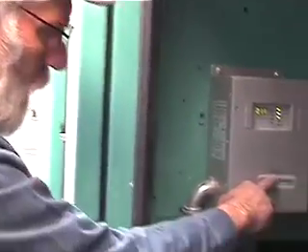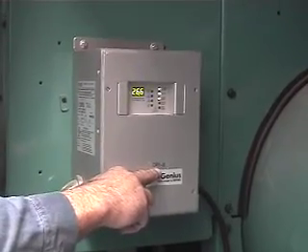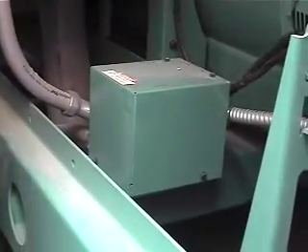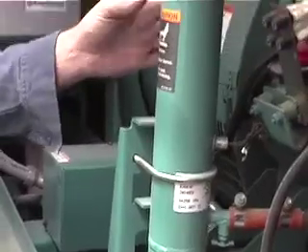Now, something I'm going to ask Randy to do here. Oh, he's already got it marked right here. OP1-8. That's going to be where your circuit breaker is that feeds the charger. And I see over here he's got OP1-10. That's going to feed your block heater. This component right here is your block heater, and as you notice, it says hot, service can cause burns. I always just barely bump it. You do always want that warm. Otherwise, that should be sending a signal somewhere saying that you've got a low engine temperature.